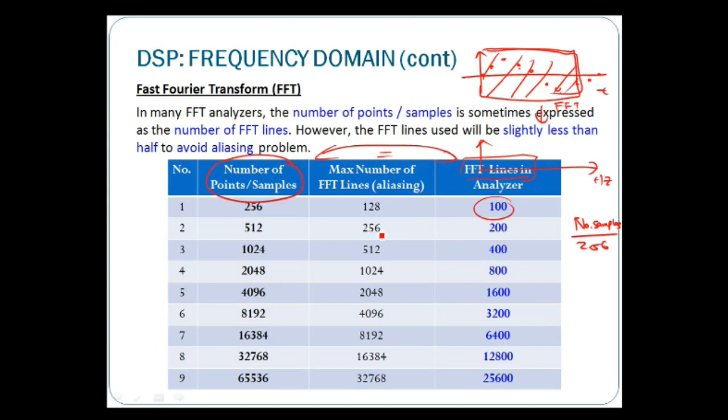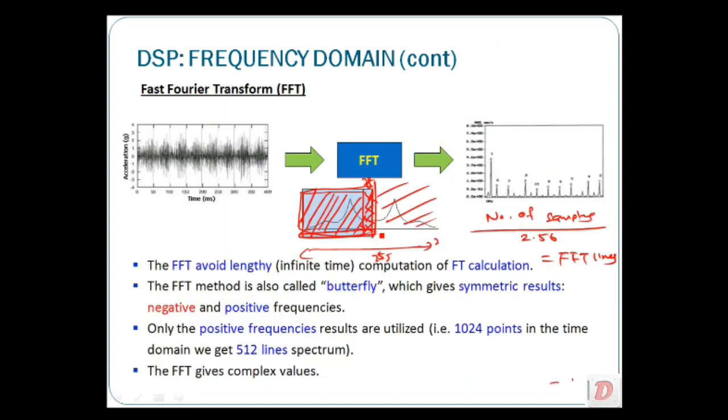It's also related to the aliasing effects. You still remember the aliasing effects. You have this anti-aliasing filter that cuts off half of the frequency that you can use. So in the frequency domain, that half of the frequency won't be shown, but will be replaced by a mirror image of the signal in frequencies.